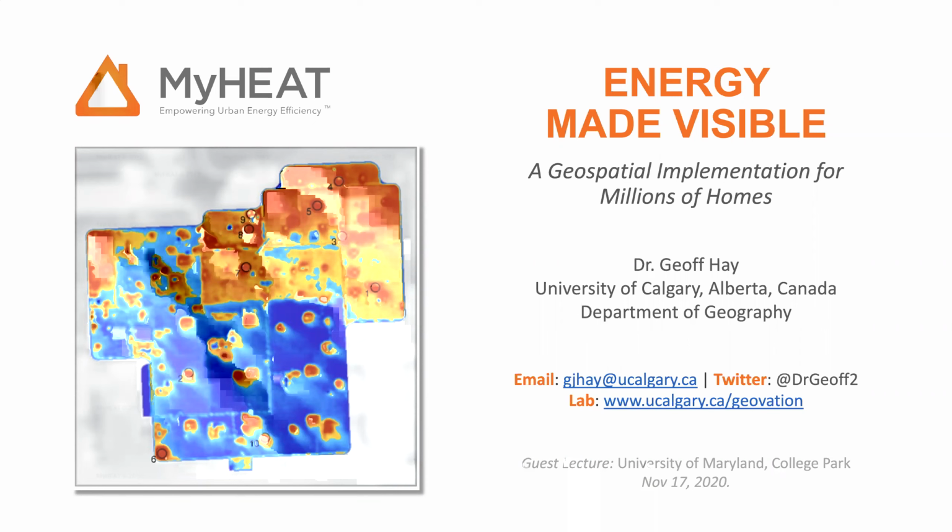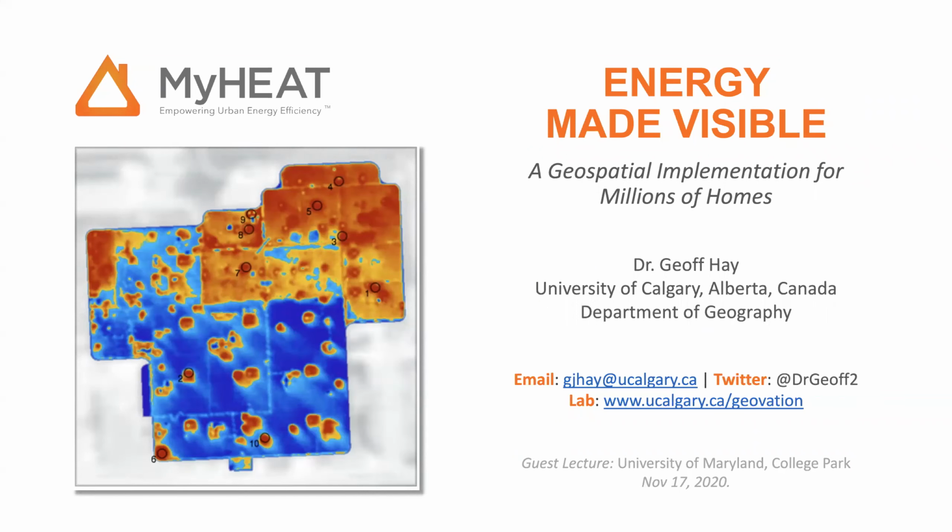This is a very, very large commercial building. The image has been resized so that it fits a very small window. But the camera that we use is a high resolution thermal camera, a camera that senses thermal radiation. We're able to convert that grayscale signal into temperature values. Here we've made it so that red is hot and blue is cool. So you can see in this image where the energy is actually leaving the rooftop of this building.